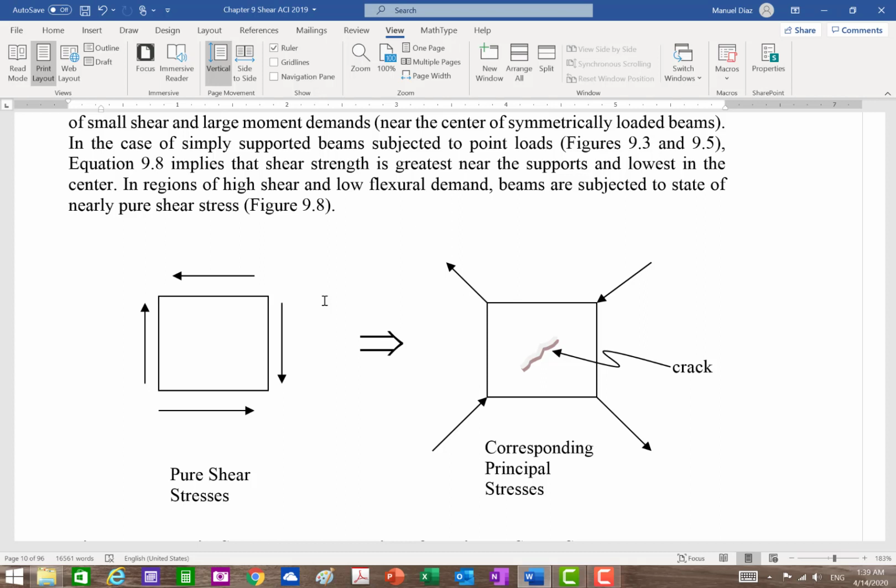And what happens on the neutral axis? Your bending stresses are 0. Yes, see, you're remembering. So you have 0 bending stresses on the neutral axis, but your shear stresses are maximum. So maximum shear stresses and 0 flexural stresses at the neutral axis. Remember from Mohr's circle, the little square element? All you have is shears.